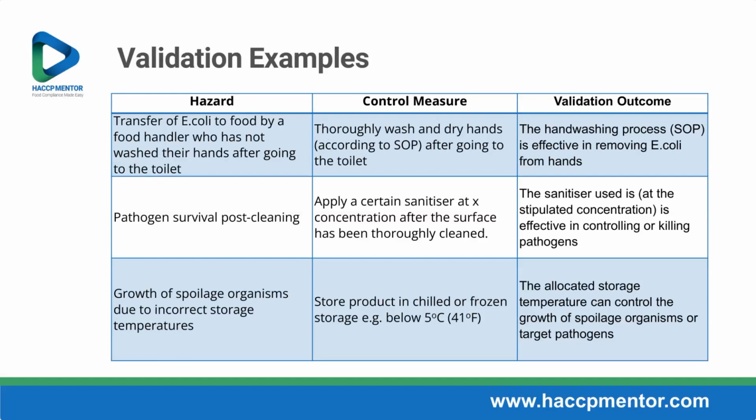If you're handling allergens in your business, and this is something that happens a lot with powdered product, if you're using a type of push-through method, so this is when you basically push through finished product at a particular quantity of the finished product for the next cycle. So maybe you've had one product go through that had an allergen in it, and now you're going to push through a non-allergenic product to get rid of the allergenic product.